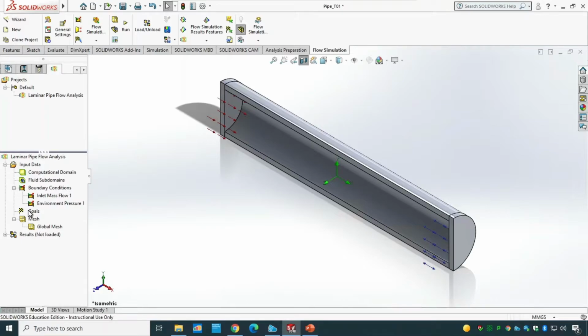In this case, I'm gonna create a surface goal. So I can go to the goal, right click, and you can see I have access to the global goals, point, surface, and volume goals, which basically means you're gonna control a volume, a point, or the global, the whole model.